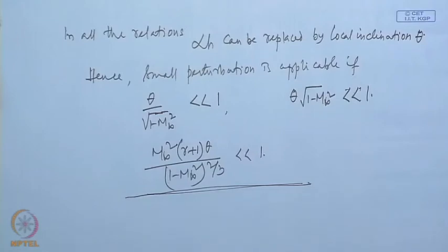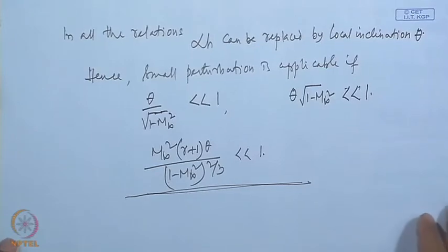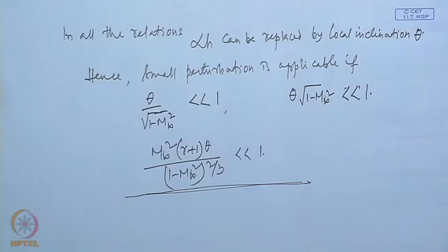So, we have considered a subsonic flow past a wave shaped wall and obtained its solution, and we have also seen the validity of these conditions. These results have shown us that a flow can be transonic for certain Mach number and body shape for a particular gas, but may not be transonic for another gas.